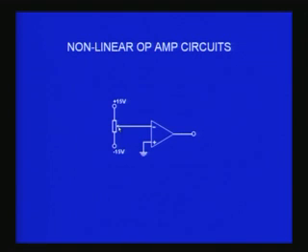So, when I move the wiper above and below that 0 point, you would find the output will shift to plus VCC and minus VCC as the case may be, because I will be exceeding that 140 microvolt range while moving up and down. Therefore, this is one way to see it in the lab, actually performing the experiment. I can use a simple potentiometer and move the wiper, monitor in the multimeter, and you would find it is changing from plus VCC to minus VCC.